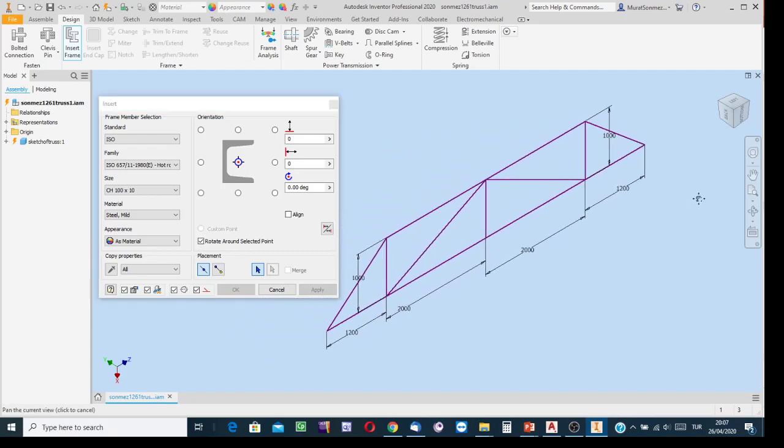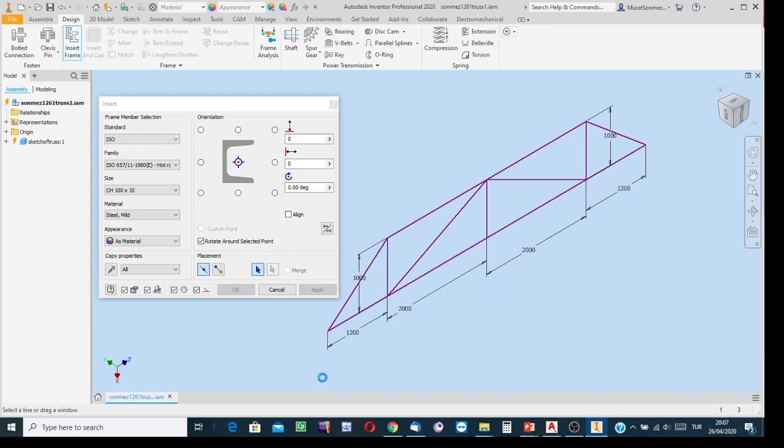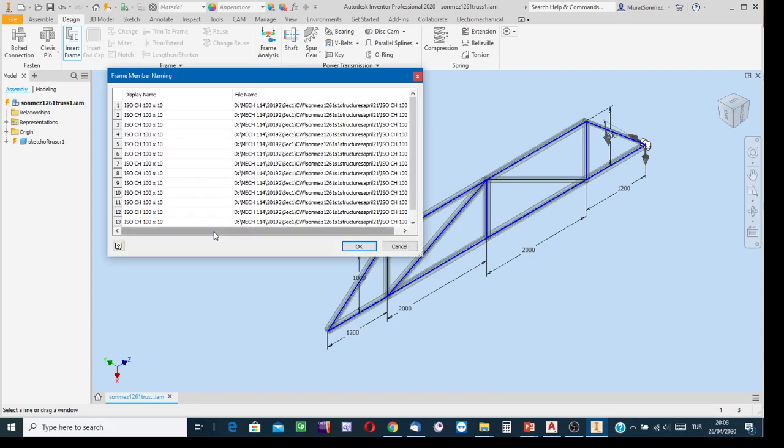Okay, and then my demo, just to highlight the value of structure creation tool. Well, to be able to prove that even for a very long truss, or in general speaking structure, time period needed to create the main part of the model is in the order of even seconds, just see my demo. Using windowing method, select all the lines corresponding to the skeleton of the truss and release the button. That is it. And then system, you see the simulation about to create. Just say OK. And then say OK.